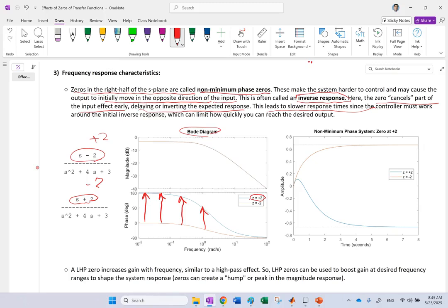But if you look at their step responses also, that's very interesting. Here, the system that has the 0 on the left-hand side, the minimum phase system, the final value it should reach is like 0.6364, and it starts at 0 and immediately moves in the direction of that and tries to reach it. But the blue system should reach a value of -6.3 or something.